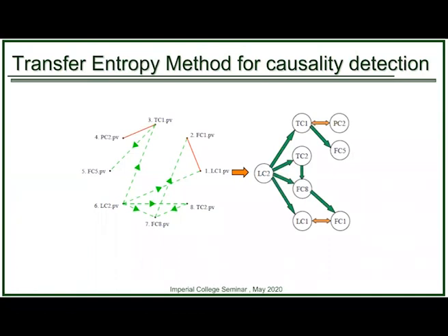We applied a transfer entropy method for causality detection. So the 8 loops that we identified as having the same oscillations, we were able to obtain connecting pathways between those 8 loops. And if you unscramble this, untangle this, this is the picture that you get, where the red line shows the bidirectional cause and effect relationship between these loops. So essentially, when you see this figure, it confirms that level controller 2 is the likely root cause of oscillations in all of these 8 loops.